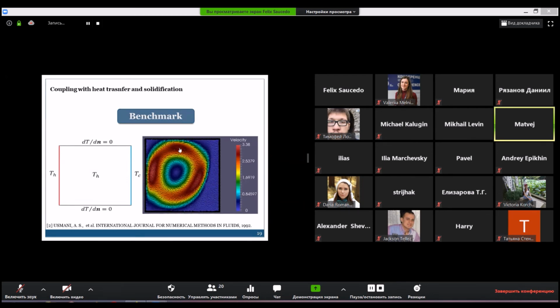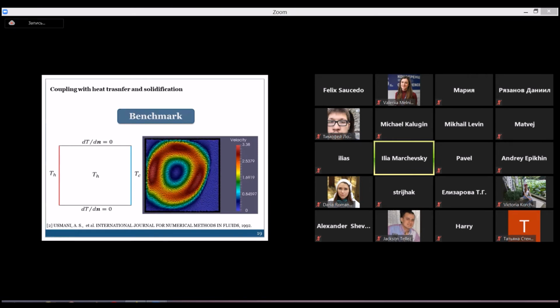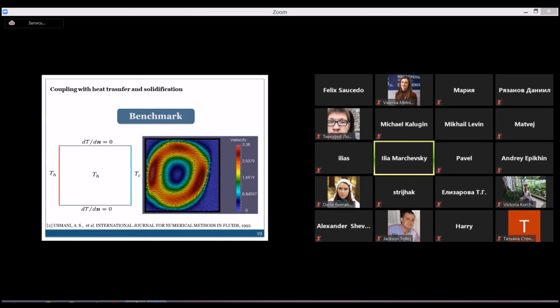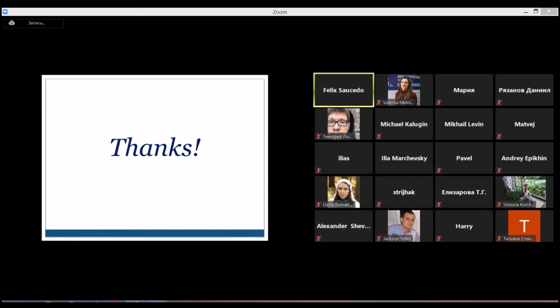More questions, please. I have one question. Dear Felix, firstly, thank you very much for the very interesting presentation. In fact, I'm also interested in meshless Lagrangian methods in computational fluid dynamics. So I have some questions related to your method. First of all, are the particles associated with masses? So I mean, do you consider material particles or no? No. In this method, the particles are only interpolation points. So they don't carry mass in that sense, but they carry all the properties of the fluid, such as velocities, pressures, and temperatures. Thank you very much.